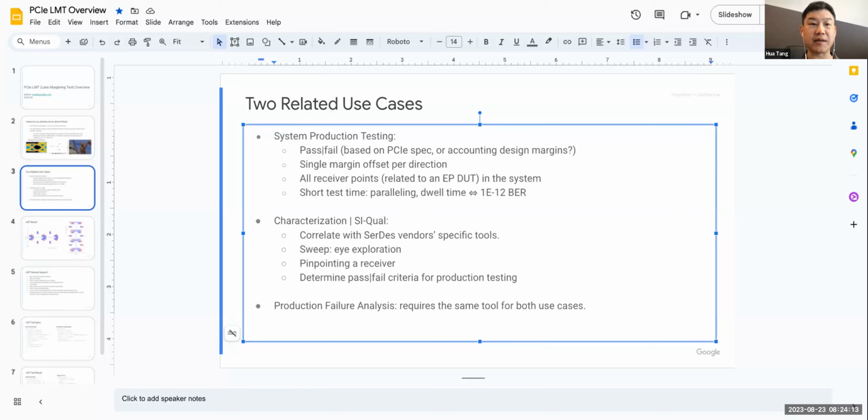You enumerate the PCIe bus, with a host running an operating system. In this case, it has to be Linux because we're using the PCI utils. Then you can conduct this test and get the signal quality of all the links on the PCIe bus. Does that make sense? But you still need the scope set up to probe the bus.